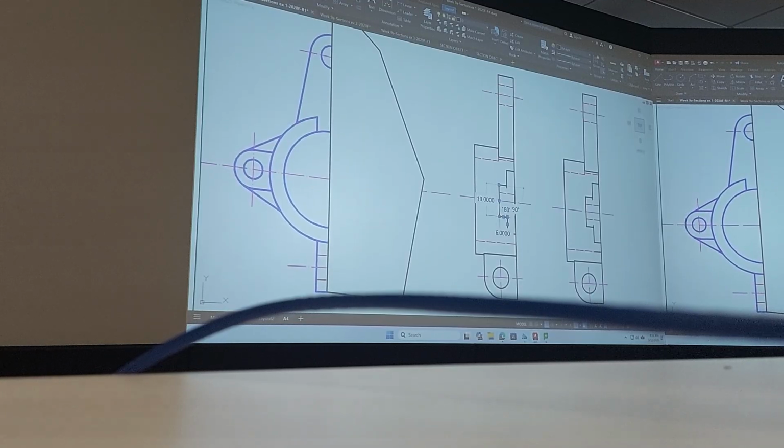You won't see it on this side, but it will be on the other side. So we can just turn this thing right away into dash lines. That's going to be dash lines just on the far side. Okay, so try to copy that over and make the cross section. I mean, finish the first one first.